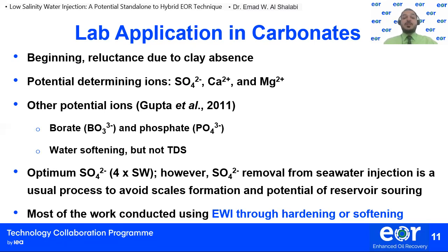Other researchers like Gupta and others in 2011 said, well, it's not all about these three ions. Other ions will be important, like borate or even phosphate, or even if you just soften the water by removing the hardness of those calcium and magnesium ions, that will give you more incremental oil. Some other researchers even witnessed a certain optimum concentration of sulfate in order to maximize incremental oil recovery by this technology.